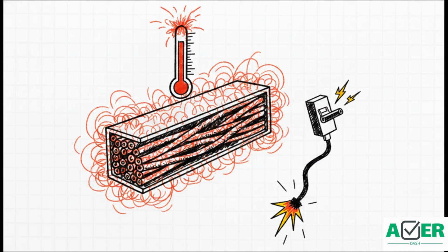Now, you've got to remember, the code isn't just throwing arbitrary numbers at us for fun. It all comes back to Rule 4-004, which is ampacity. Think about it. When current flows, temperature naturally increases, right? If you pack way too many conductors into a closed cellular floor, all that heat gets trapped. There's nowhere for it to go. This rising temperature destroys insulation, it risks dangerous electrical fires, and it causes constant nuisance tripping of sensitive circuit breakers. So this area limit is fundamentally a thermal management rule.